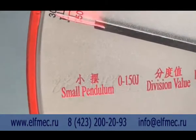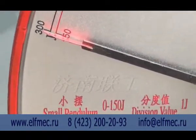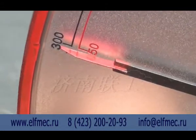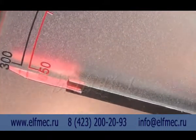Adjust the big pendulum pointer to 0. Firstly, make sure the pendulum is in a vertical position and motionless, and pull the pointer to the maximum energy line. Use a wrench or hammer to tap on the fork slightly. When the pointer presses the fork, make sure that the pointer points to the maximum energy line.